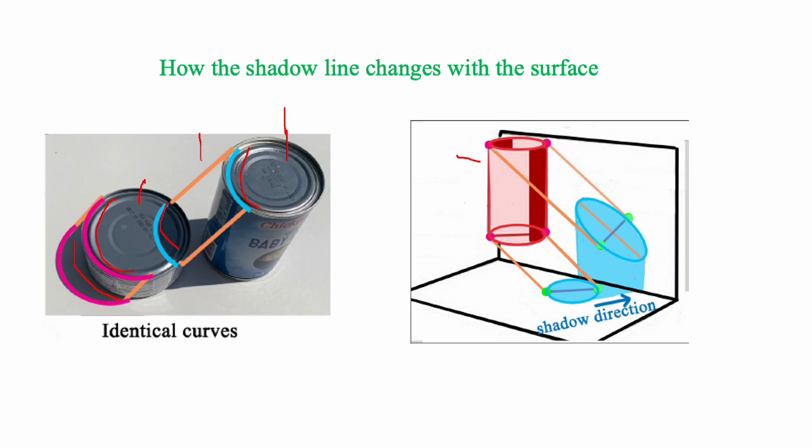For this floating cylinder, start with the shadow direction and connect the two ends of the major axis of the base to find this ellipse on the ground. The shadow then goes vertically up, defining the width of this shadow, and to find the tilt of this ellipse, draw light rays from each end of the major axis of the cylinder.